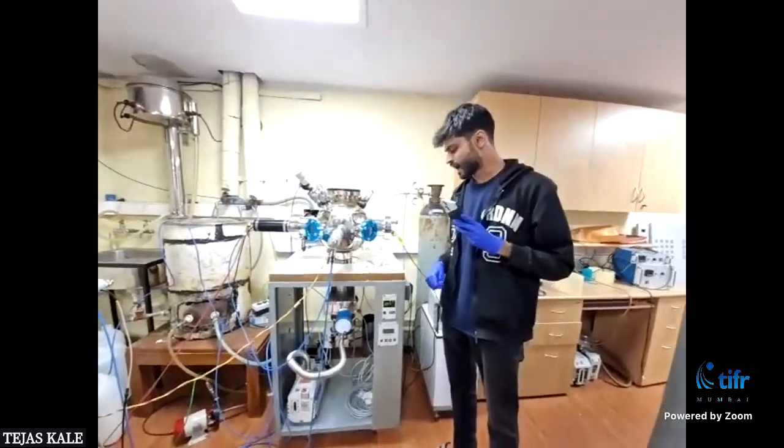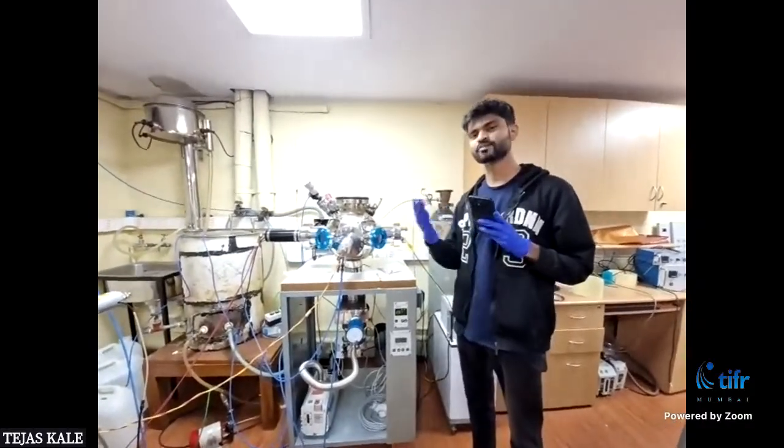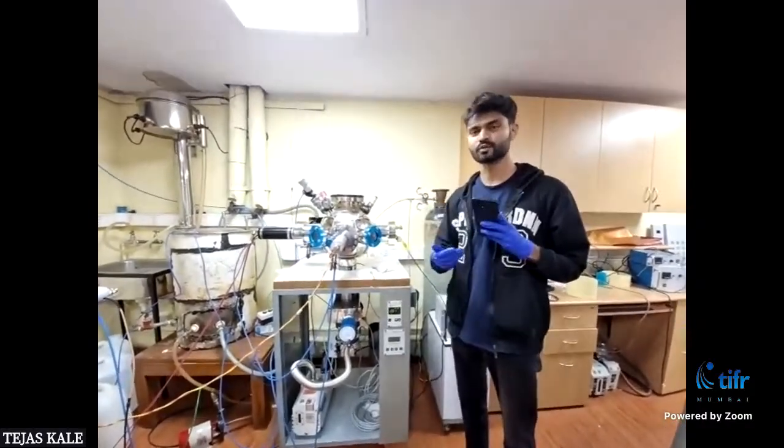You must be hearing this sound. These are our pumps, which are creating a vacuum of 10⁻⁷. When we introduce a sputtering gas, the pressure will go up. We are using argon gas as the sputtering gas inside this system. And in this system, the vacuum is 10⁻⁷, unlike the MBE machine that you saw before,